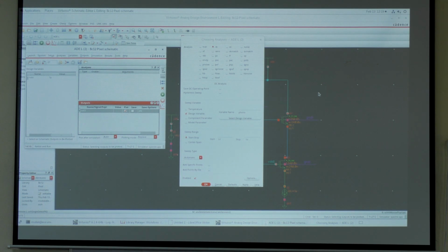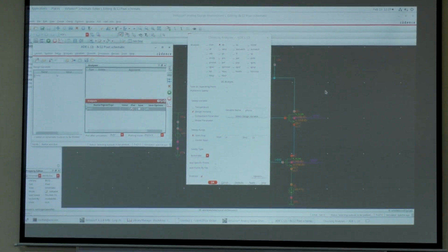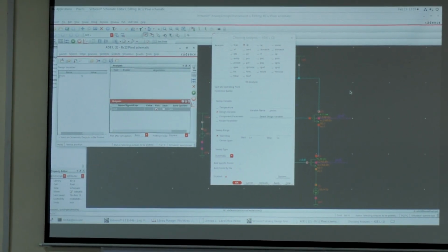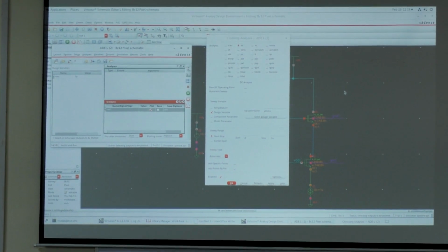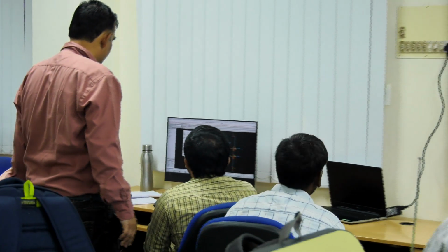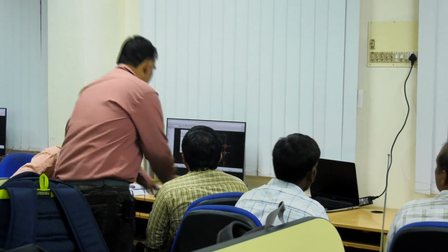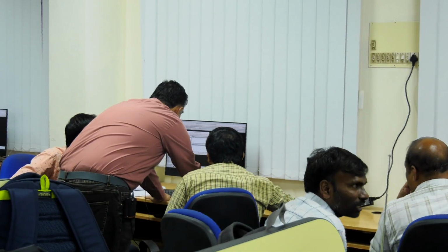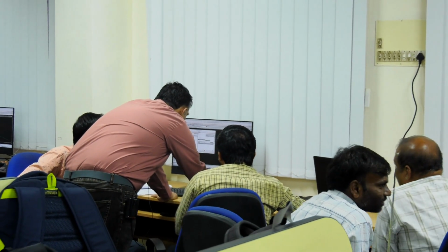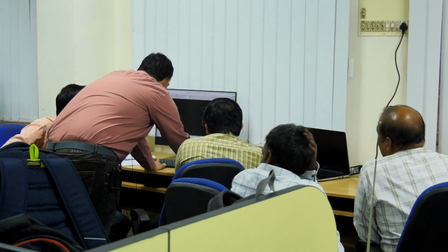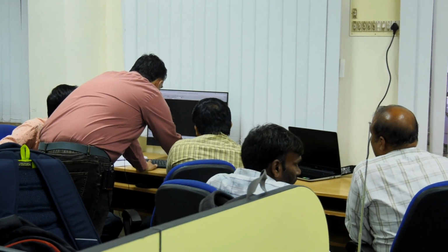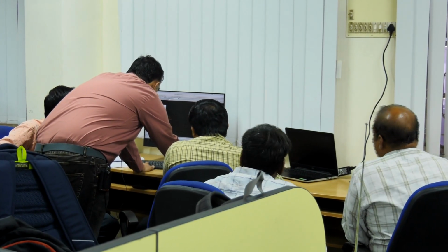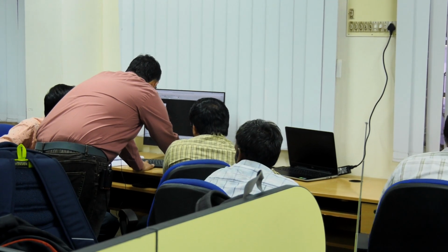So I'm getting a logarithmic response. So till here it's dark. Here you can see the scale is log and it's going down. Actually, a better way would be, got it? Okay. The only thing which you have not done is you haven't told where to see the output. I want to see the output at this point. Okay. That's it. Let's simulate, and if you have done everything correct, hopefully we will get a result.